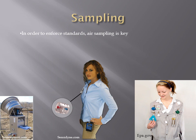After the given amount of time, the filter may be weighed to determine the amount of dust collected on the filter. This mass of dust can then be correlated to the amount of air that came through the filter during a certain amount of time to give a concentration expressed as mass per volume of air.